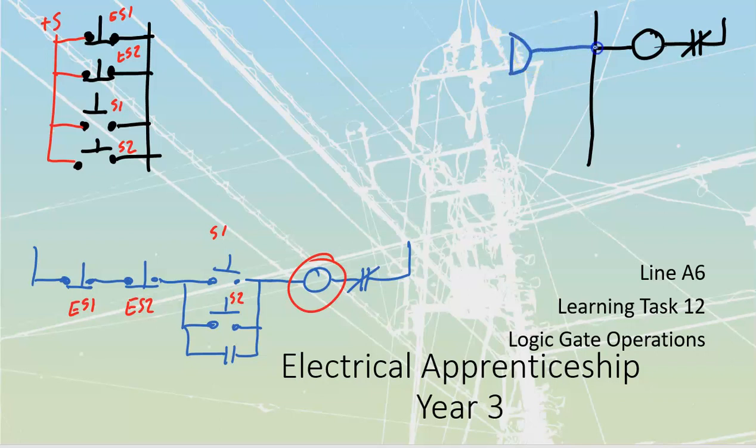That AND gate is going to go out to here. That AND gate is then also going to go out to another AND gate. Remember how I said that we take our stop signals and we combine them through an AND gate? Like that. That's what we're going to do over here. We're going to take that AND gate and run that down into that AND gate over there. This is done inside of a program. We use drag and click boxes. It's called function block programming. It gets really intuitive later on.